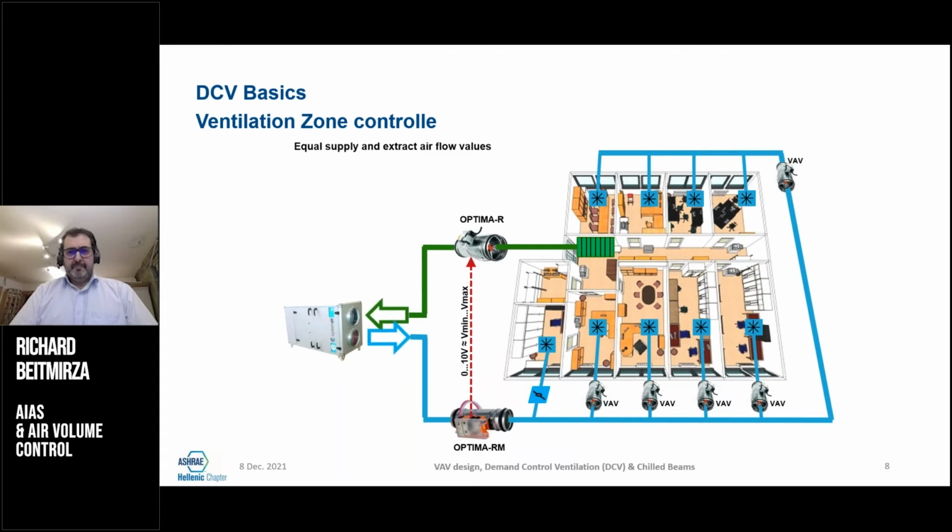Things get a little bit more tricky once you have an open platform or multiple offices where you need to mix between constant demand or a constant load room or a variable room. Here is a very good example of how we try to save money, not only by bringing the right air into different zones, but also to try to extract in a collective way.